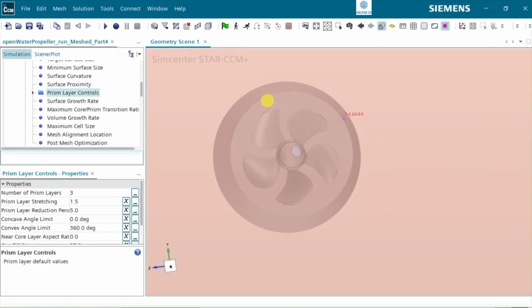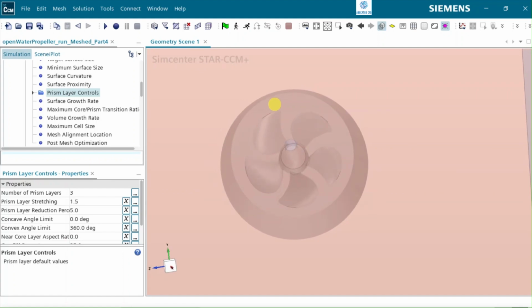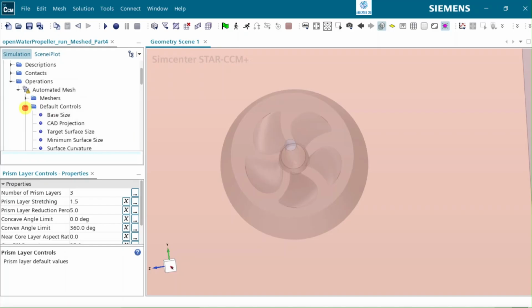One idea is to add prism layers on these interface surfaces. This interface is only used for data interpolation, so we are not applying boundary layers here. The goal is clean meshes on both sides, with good alignment and near orthogonal cells.